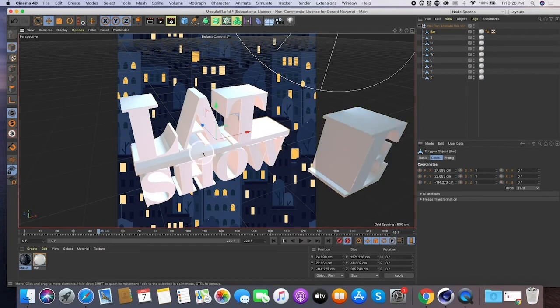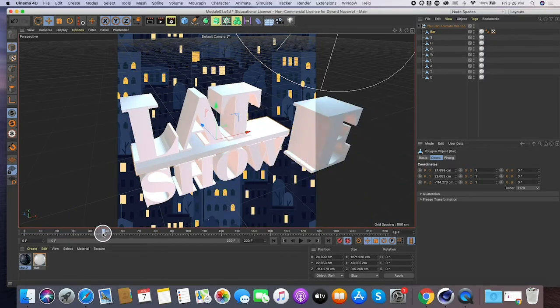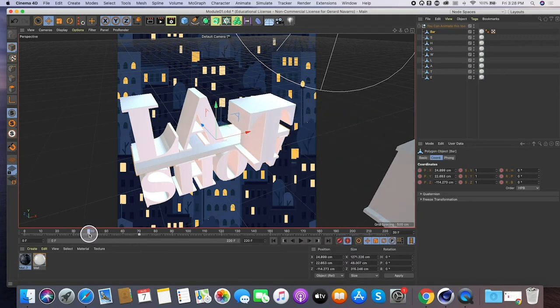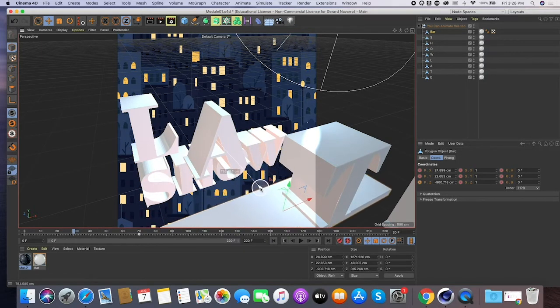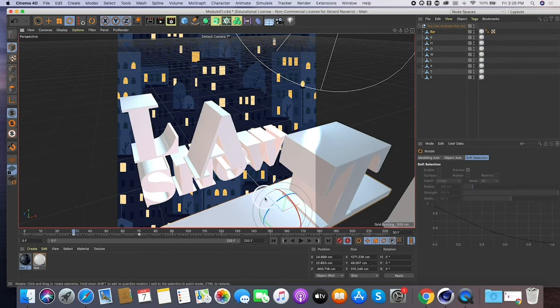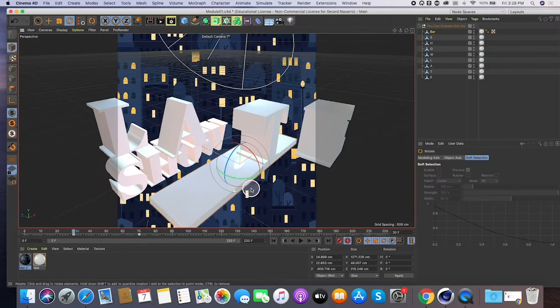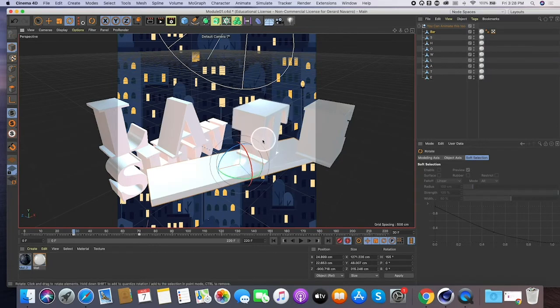You can also animate other things like rotation as well. So for example, for our bar, let's add a keyframe over here. So maybe it will settle at frame 70. Let's add a keyframe over there. And then let's move back. So for our 30th frame, I'm going to move it away from the camera. At the same time, I will use the rotate tool. So let's just zoom our camera, and then let's just rotate this maybe 90 degrees or 150.